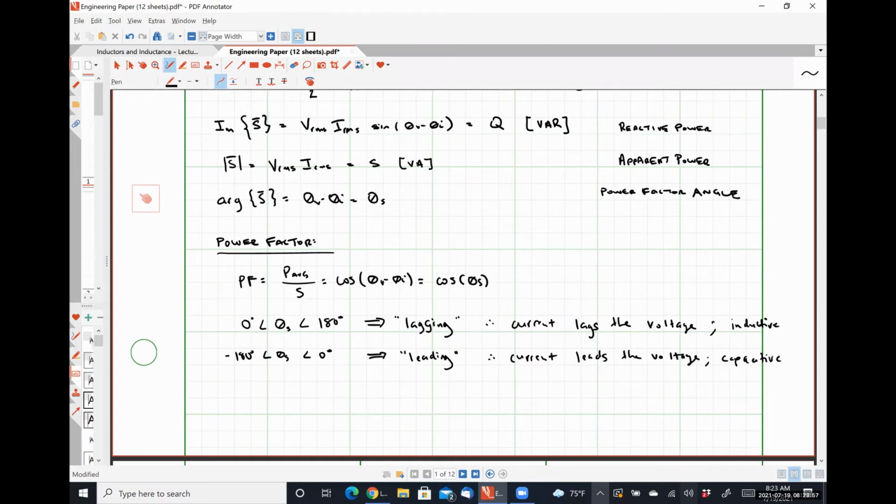When our power factor is exactly +1, -1, or 0, we don't consider those to be leading or lagging, right? So for a power factor of unity, or 1, the voltage and current don't lead or lag each other, because they have to have the exact same phase angle.